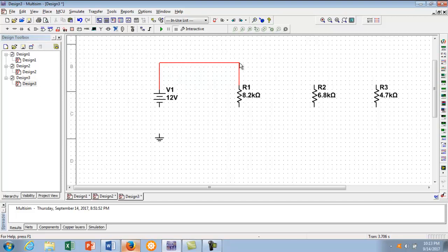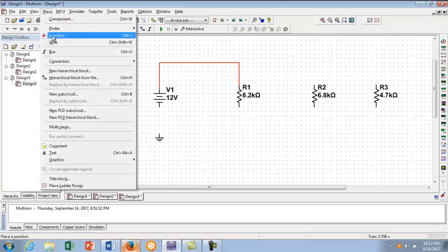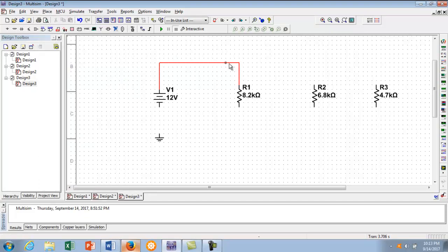And then you realize, wait a minute, I can't place in the component junction. You can do that. You can place another junction point here to keep connecting along the way by either placing a junction, and then clicking, and that immediately gives you the ability to click over, or you can just click on the previous resistor and click backwards. Both are suitable. Placing a junction helps you at times when you don't want to have to delete a trace or you have to connect something that won't connect on its own.